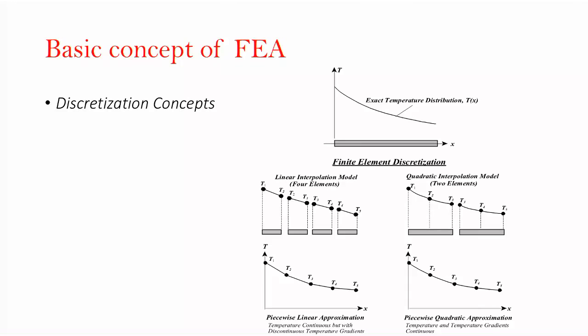So instead of having only 2 points at the ends of the line segment, we added another node at the mid-edge of the element. So these are the 2 ways to increase the accuracy: increasing the number of elements, making the elements smaller to capture all variation and changes in that area, or using a higher polynomial function as the shape functions.